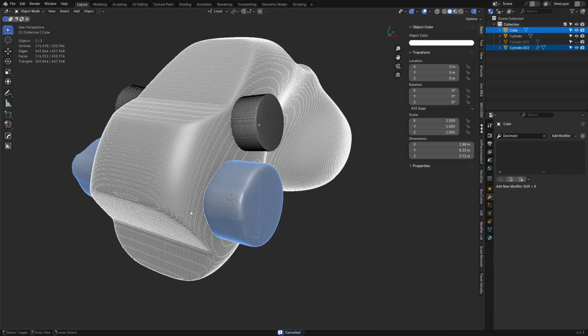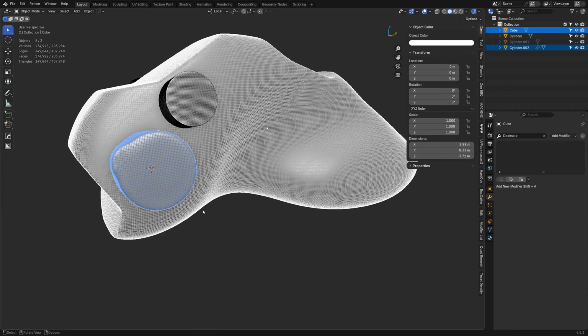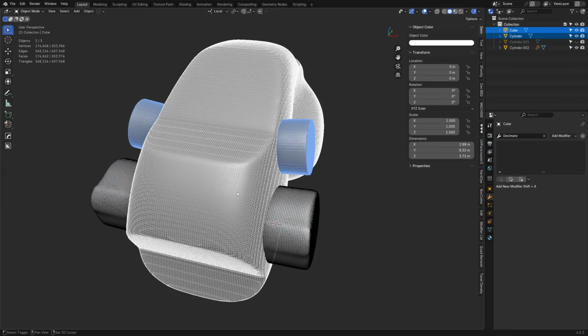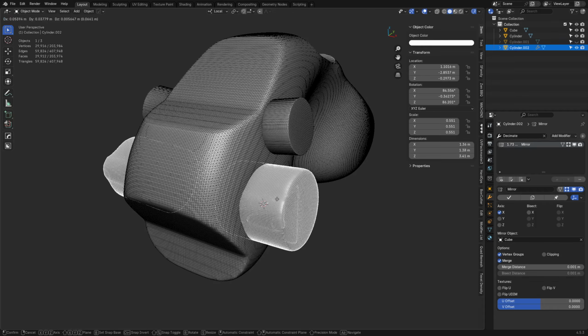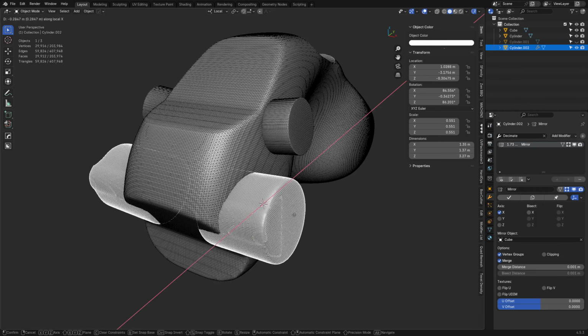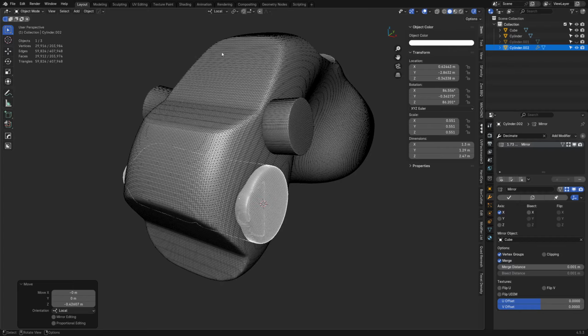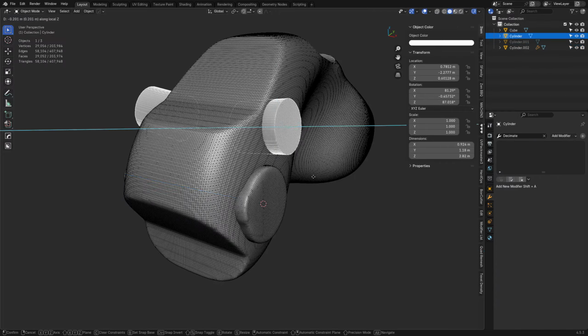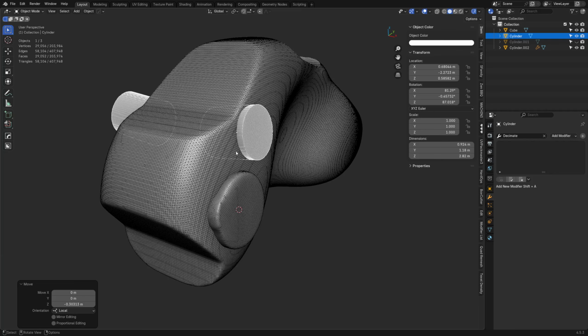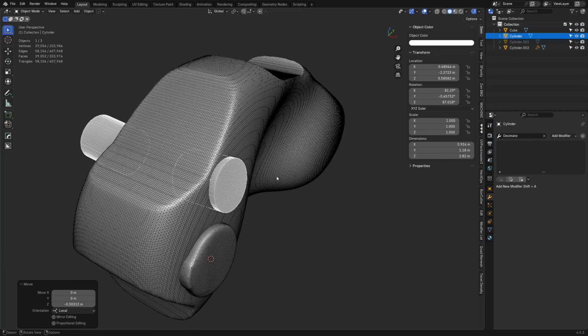So like if we do a Boolean subtract, we'll get something like that, right? But if we do a Boolean union, it's not really needed to do unions. It's actually better to leave your mesh separated if possible. So if these are supposed to protrude, maybe we leave them protruding like that. We don't try to modify it too much. We set this back to global if we want. Local, you can access at any time by hitting Z, like in our case, Z twice. You can still do that. So we don't have to actually use local every time. We can use global, and then when we need local, just tap the axis we want twice.